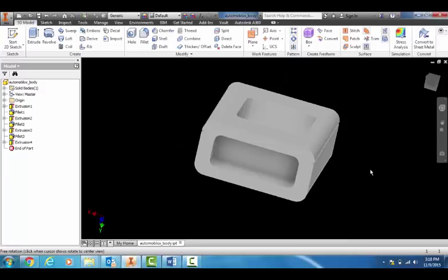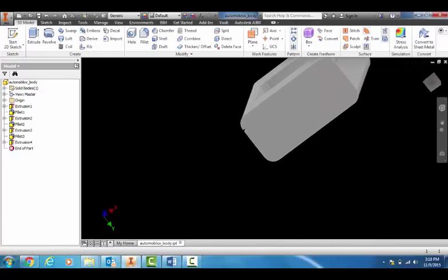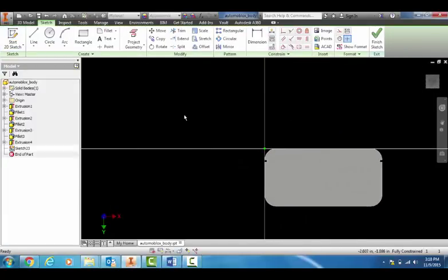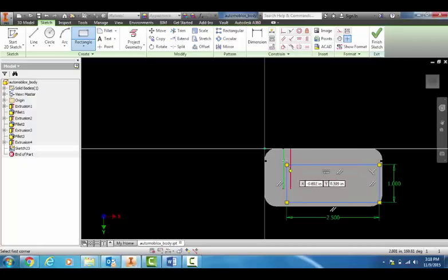Okay, so let's turn our object around, center it here, click on this face or plane, start 2D sketch. Let's come back to our rectangle tool here. Okay, start drawing it out. Okay, it's, if you recall, 2.5 inches, tab button, by 1 inch, enter. Okay, now we got to dimension it and center it. So we hit the dimension button up here. Okay, click on that part, click on that edge.